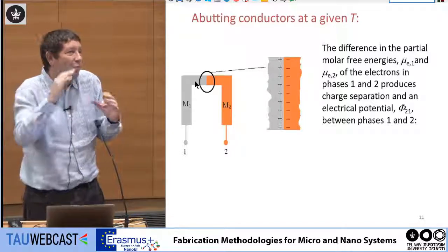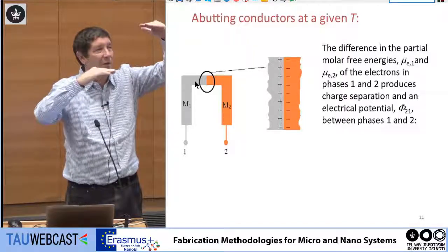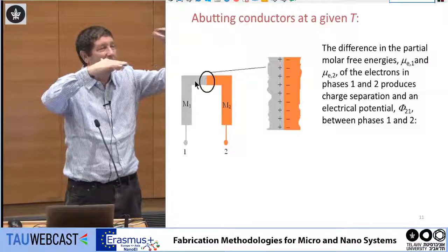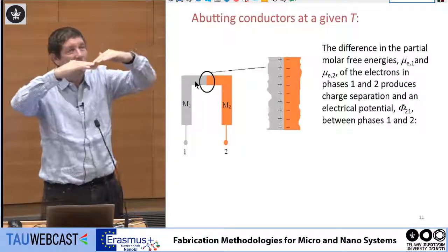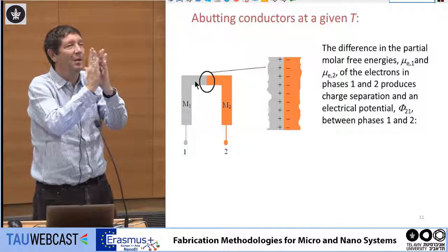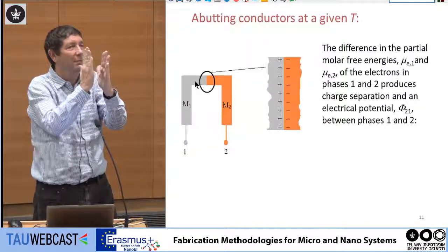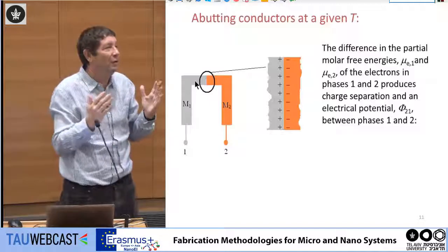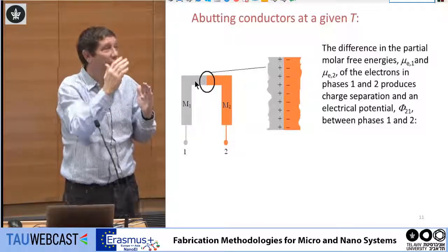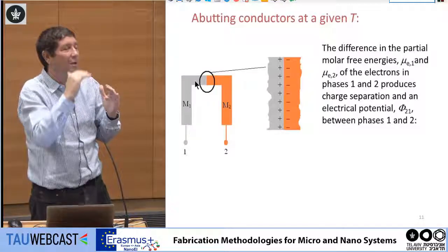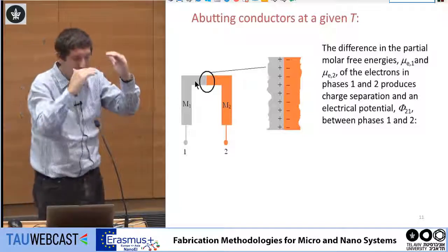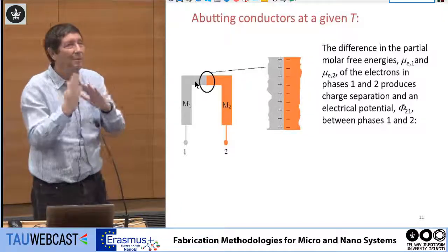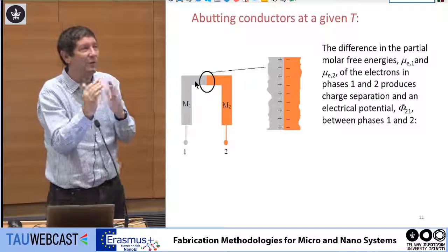But even with two metals, one with a higher Fermi level and one with a lower Fermi level, electrons will go from the higher to the lower. So you will generate some electric field because you have an initial flow, but this initial flow is not forever. This initial flow by diffusion, by the difference in the potential, will be balanced by the formation of an electric field inside.